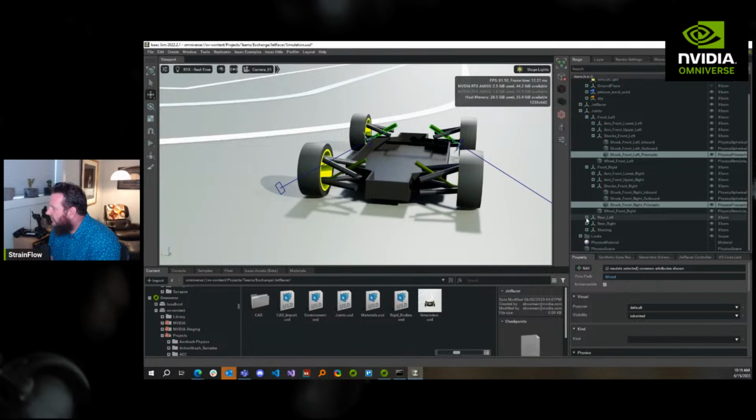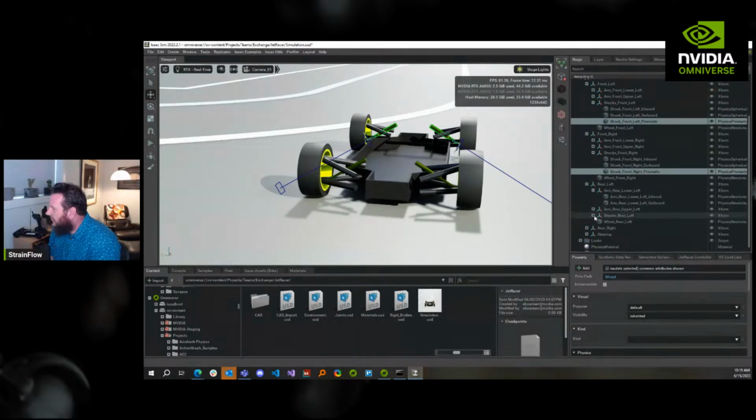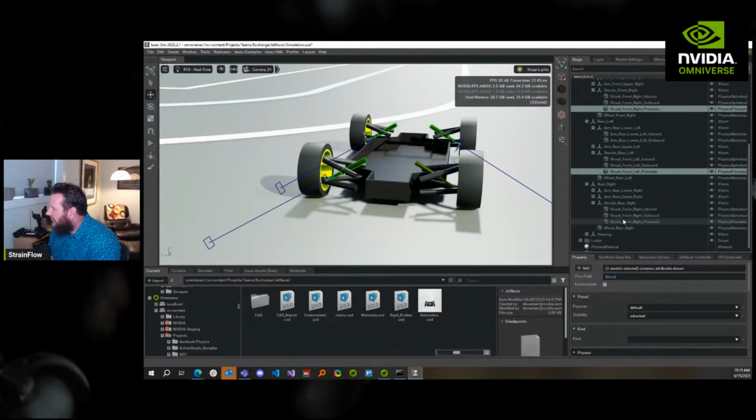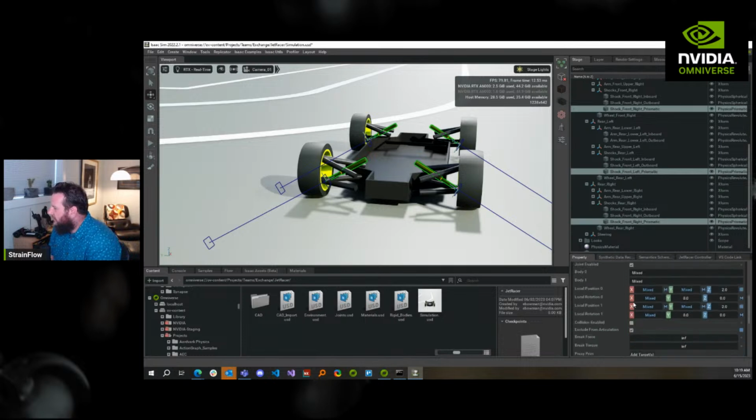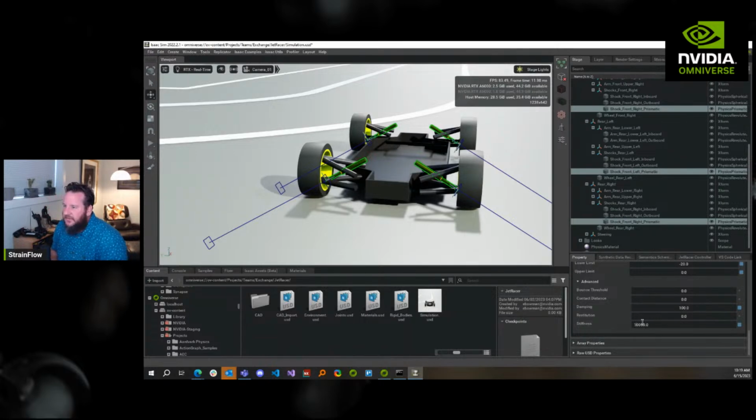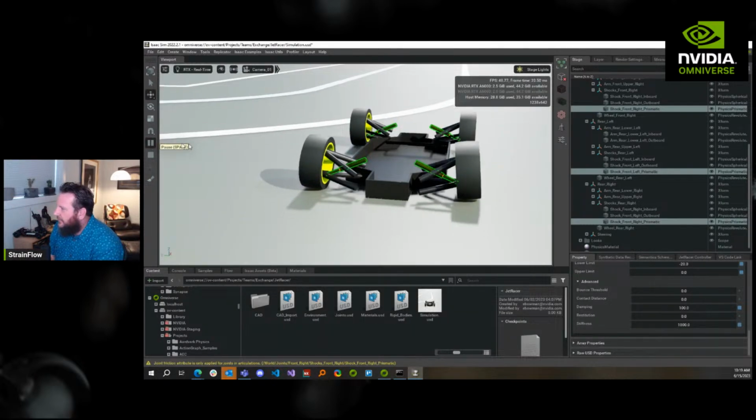I can select all of my springs at once here, and I can add them together so they kind of stay together. Right now it's at 10,000, which means that's pretty stiff. 1,000 should be that under 1 kilogram, it should flex a millimeter. Let's see how that looks.